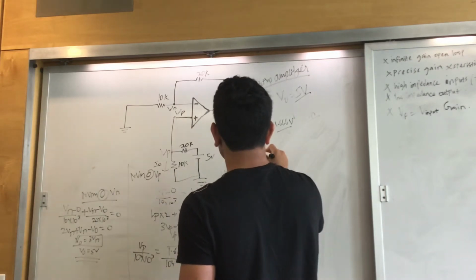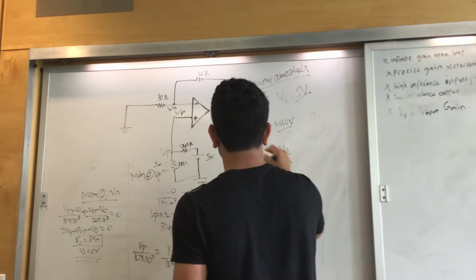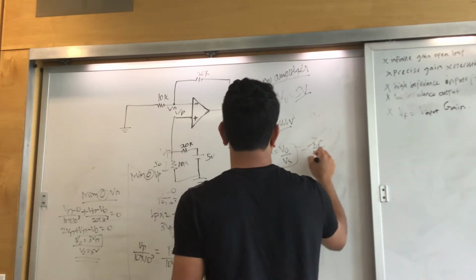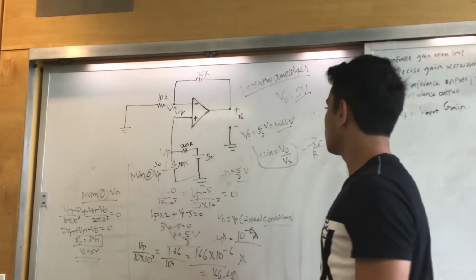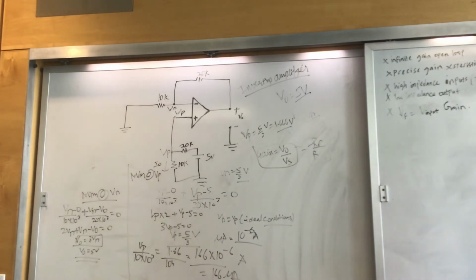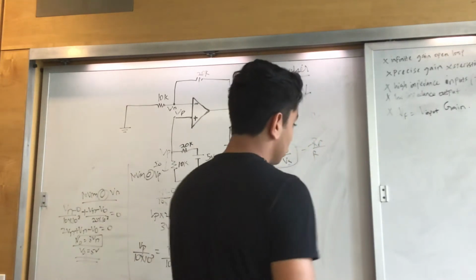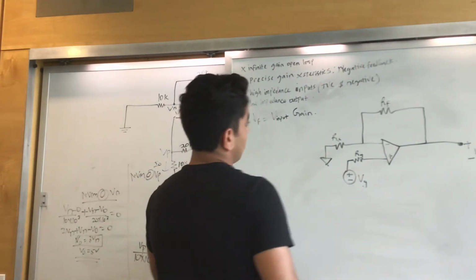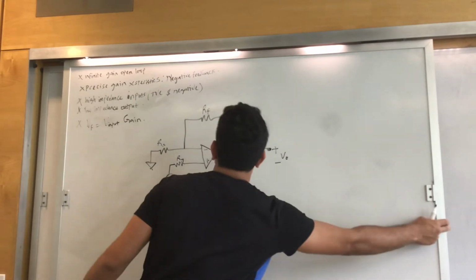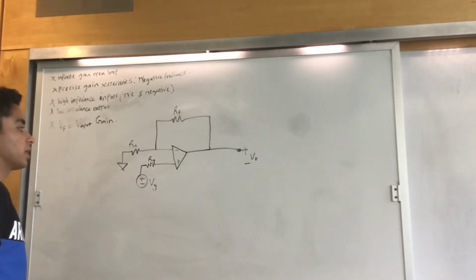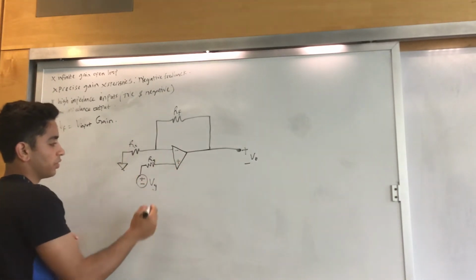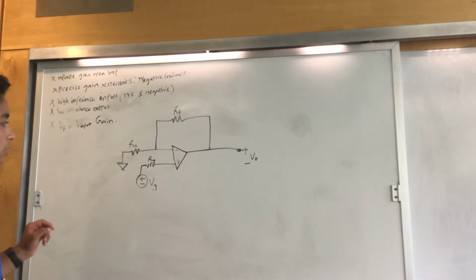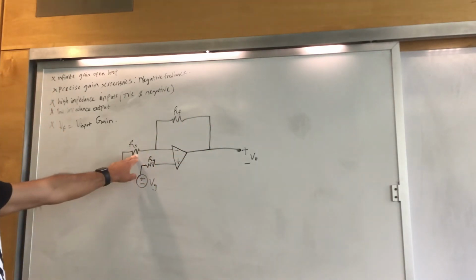And then the gain, this is V naught by Vs, or minus RF by RS. So coming to and comparing that with a non-inverting amplifier. So this is the example of a non-inverting amplifier, and in this we can see that the voltage source is connected to a non-inverting input, which is positive, and in the same thing we still have the V naught going to the inverting input.